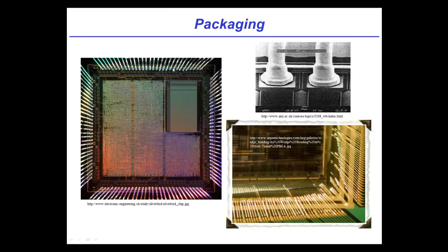All right. So packaging, we haven't really covered what happens to the die. How does it go from a little silicon die to the, I guess, black square or rectangular enclosures that most people conveniently call a chip when they see it sitting on their motherboard? There's lots of different ways, and so let's touch on just a couple in 2 different slides. The oldest traditional thing that happens when you want to go from a die to a package, and a package is the thing into which you're going to place the die, and that's what's going to bond onto your printed circuit board. And Vivek's going to touch on that in a minute a little bit more.